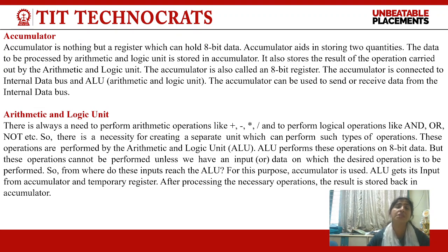Now coming to the first, accumulator. Accumulator is nothing but a register which can hold 8-bit data. Accumulator aids in storing two quantities. The data to be processed by the arithmetic and logical unit is stored in the accumulator. It also stores the result of the operation carried out by the arithmetic and logical unit.